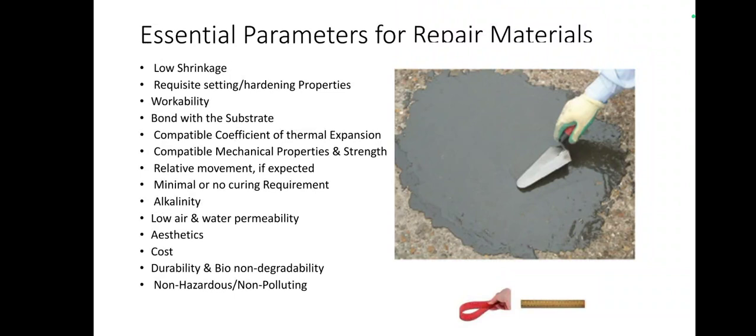If the next day we just continue the work and place new concrete on the old concrete, a weaker zone will be created at its junction. So bonding won't happen and it will act as a failure medium. In order to avoid that, the old concrete should not set until the new concrete is placed.